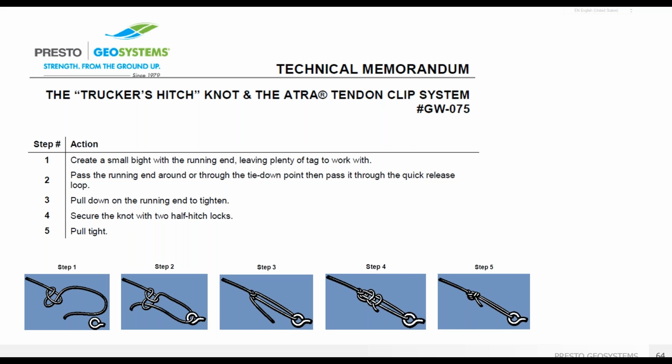One recommended knot is known as the trucker's hitch knot and is a self-binding knot common for tying loads to secure them to a fixed point. It can be tied anywhere in the standing part of a line and can create high tension lines that are used to safely secure heavy loads. This is what that knot looks like. But again, one of many possibilities.